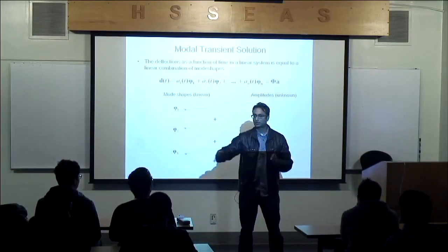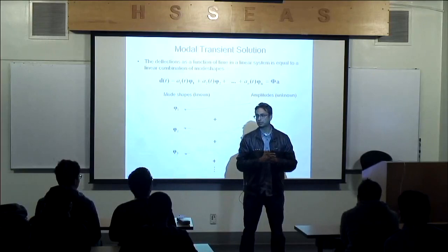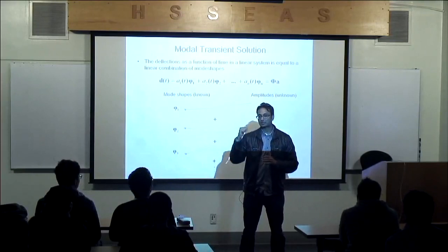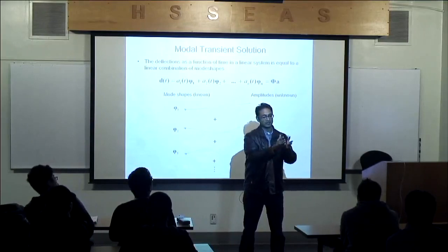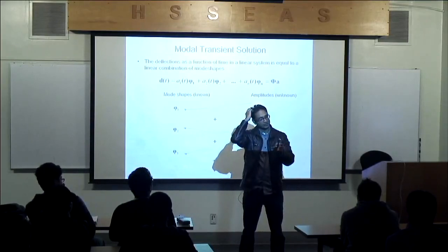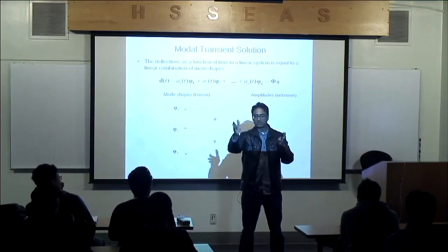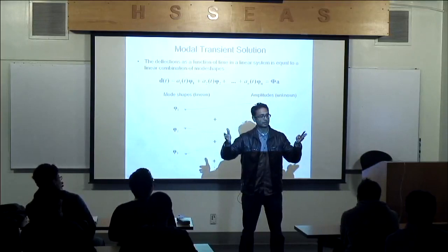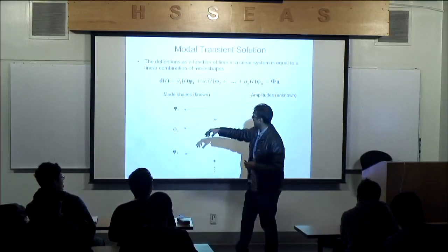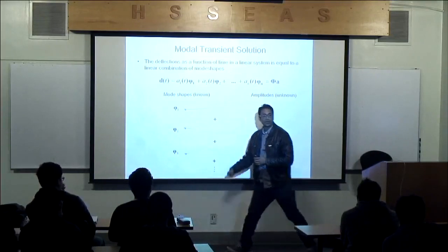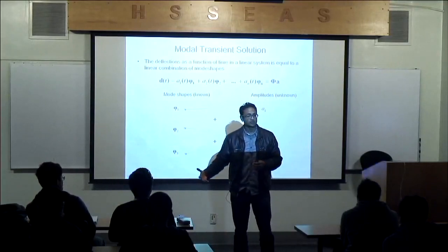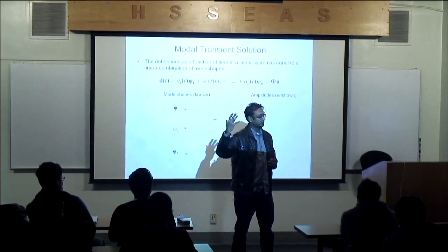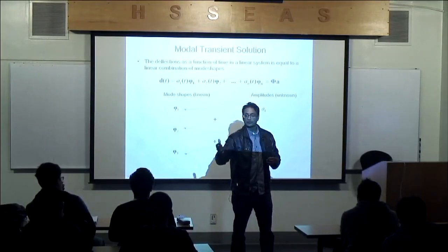where I discretize the time domain, the way I did it, I'll have to solve a million by million matrix at every time step. But what's amazing about this is that if I took that 1 million degree of freedom system and I calculated the DNA, what I call DNA, the frequencies and mode shapes, up to, say, 100 hertz, because that's what I think is relevant to the problem, and there's only 40 of them, so then if I have 40 mode shapes now that I'm considering, how many amplitudes do I have? 40. How many degrees of freedom do I have? 40. So I've taken a 1 million degree of freedom system that takes forever to solve, and I can now do it with 40